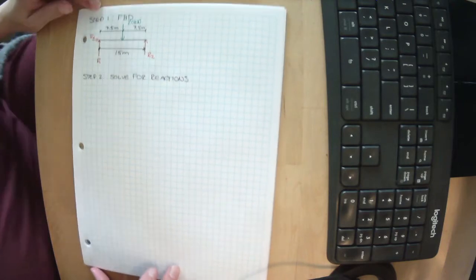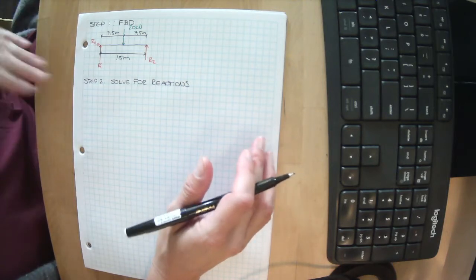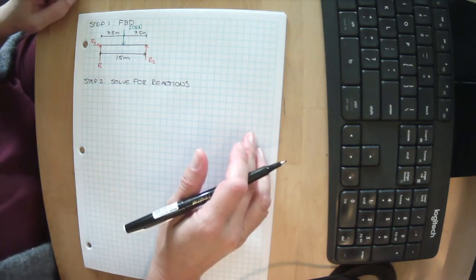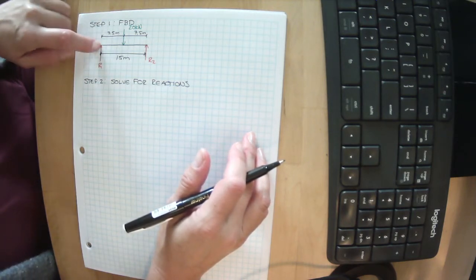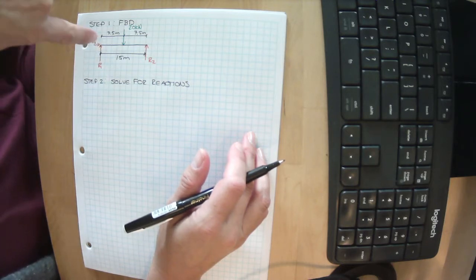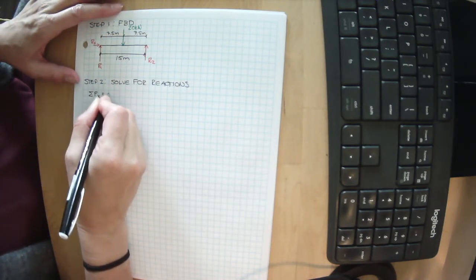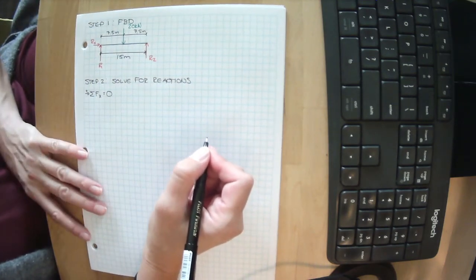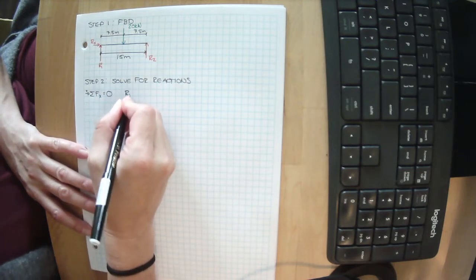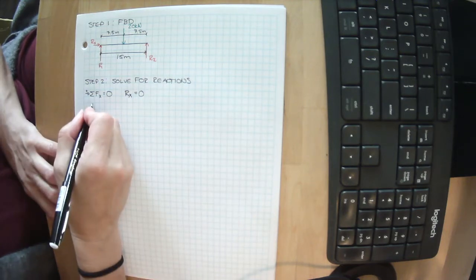All right, we're pretty good at this now. We know that we can solve all of the forces in the y direction, the x direction, and we can pick a point to spin about. I've told you again and again and again that for solving for reactions, I'm pretty lazy, and I normally put my pin right here, or the spot that I'm imagining I'm trying to spin this about right here. So let's sum our forces in the x direction, and we want to know what it takes for this to be in equilibrium, or for the forces all to be 0. So we have Rx, okay, Rx equals 0. That one's nice and easy.